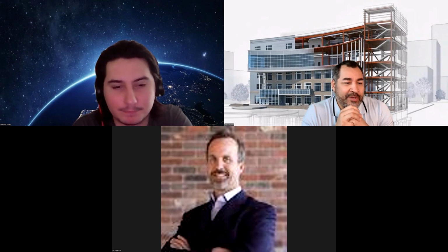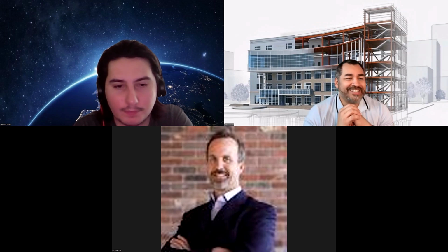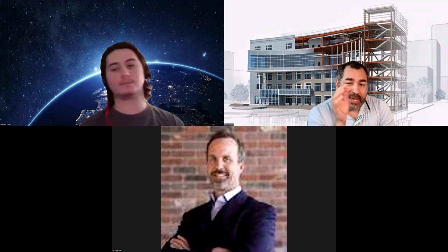That's why I never bring in architectural dynamic blocks into Civil 3D, especially if it's third party from somebody else's engineering or architecture firm. I'll typically explode those items before I bring them into my project. I had problems one time with an architectural company. They copied a block over to the designer, and then the drawing started crashing and crashing, so I had to do a process of elimination to figure out what they did.